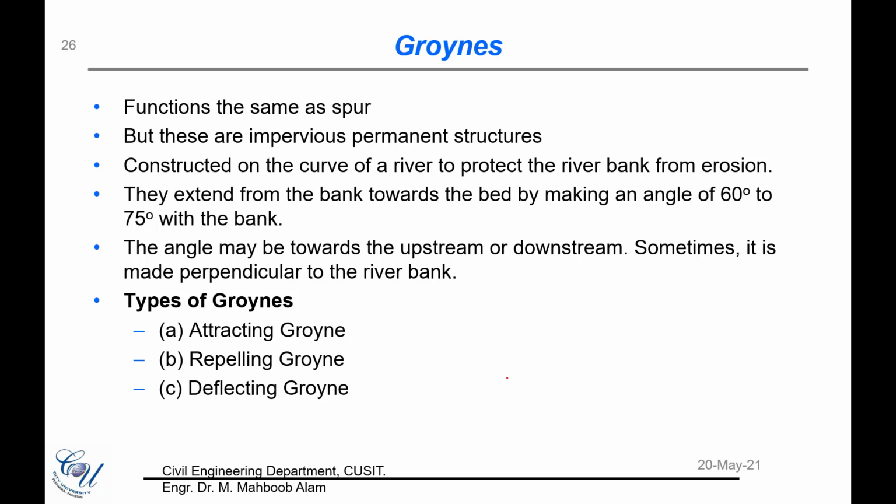And their inclination towards either the upstream or the downstream direction makes it possible to either attract the water towards the banks, and hence the name attracting groin, or to repel the water from the banks towards the main river, and then they are called repelling groins. So this depends only upon what kind of inclination you are giving to the groin, so that the water is either attracted towards the bank or repelled from the banks.